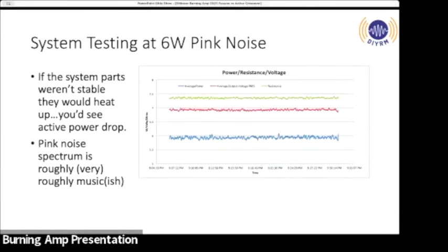6 watts or so RMS into it. Or I shouldn't say 6 watts RMS. There's no such thing as watts RMS. Watts continuous. 6 watts continuous into it. If things were heating up so much, and this is pink noise, you would see the power dissipation drop because the impedance would be going up on all the things that were heating, right? And you would measure a very different frequency response from the system.